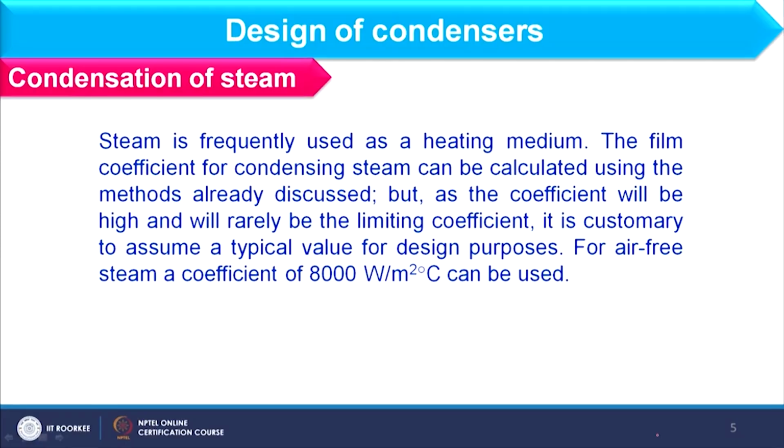Okay. And why am I considering both flows? Because when the flow is occurring inside the horizontal tube, you cannot predetermine which model is applicable. So, you have to use both models and choose the higher value of heat transfer coefficient as the final value. So, in this way we complete the design of condensers of shell and tube type, and further we will discuss a few more points, and here we have the condensation of steam.